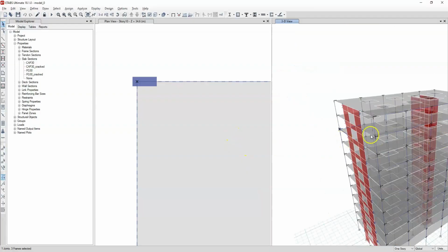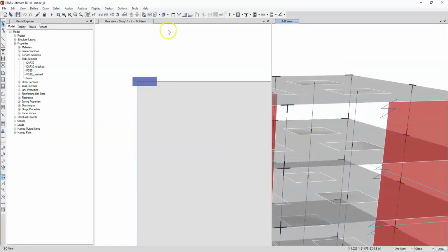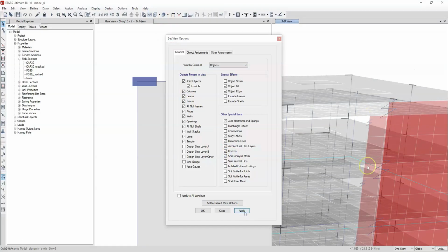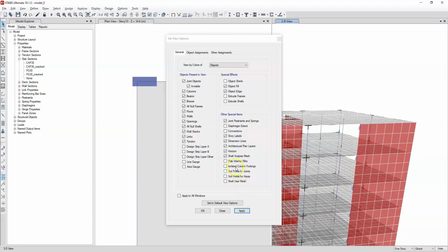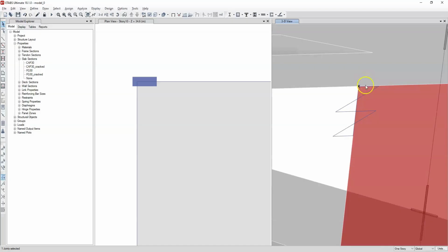Another very important aspect is the connection between the beams and the walls. Between the beams and the walls, there is a joint that shares the connection between the beam and its entry into the wall. This joint has a stiffness on the wall side that acts as if it were a torsional stiffness in the direction perpendicular to the plane of the wall. In other words, it is neither a typical plate behavior nor a membrane behavior. It is a membrane torsion.